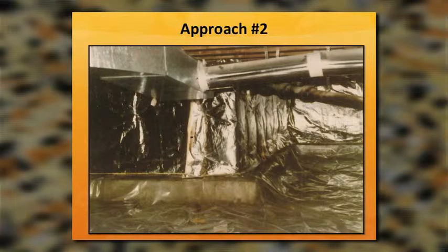And that way, we don't have to insulate all of our ductwork. So if you notice, this ductwork actually sits down below our floor. So even if we did a net and blow, we'd have to insulate that ductwork. And that gets to be tedious and expensive, and it's really easy to miss spots. And this approach with the barrier on the floor and the insulation on the foundation walls and making sure that all our crawl space vents and our rim joists are sealed really well works good, and it's economical.